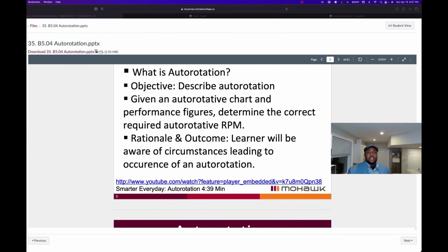Flight at 175 feet, somewhere here, with a speed of 20 knots is also a place that you should avoid. The reason you're avoiding this again is because yes, you have enough altitude, but you don't have enough forward airspeed. On illustration B, you're flying at just 10 feet above the ground, even though you have good forward airspeed. Continuous operation here is not advised because you are unlikely to have a successful auto rotation.